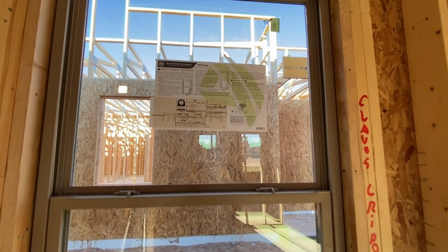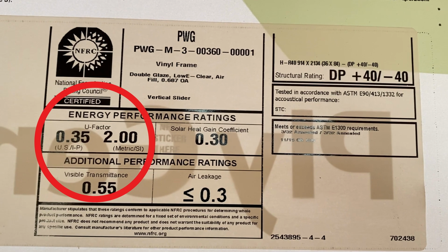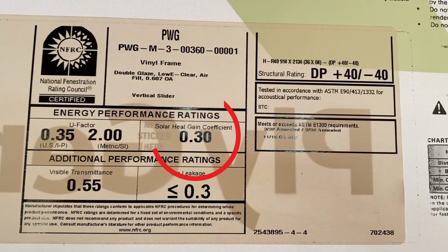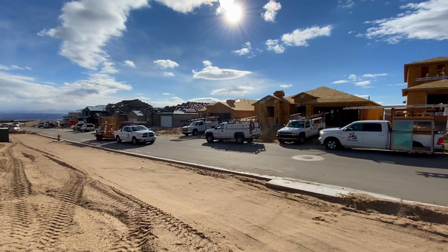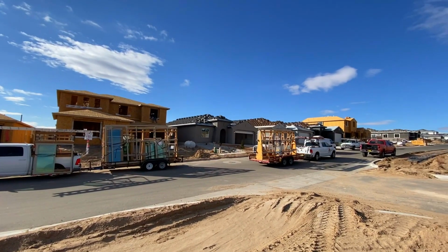Let's start with windows. Be aware that the U value for windows has decreased from prior codes, requiring them to be more energy efficient. Also, you need to pay attention to a window's solar heat gain coefficient rating, which is the ability of window coatings to reduce heat gain from the sun. For example, in Climate Zone 4, which includes Albuquerque and Rio Rancho, the new energy code requires an SHGC of 0.40 or better. Many big warehouses stock Energy Star windows with a rating of 0.30 at no increased cost.